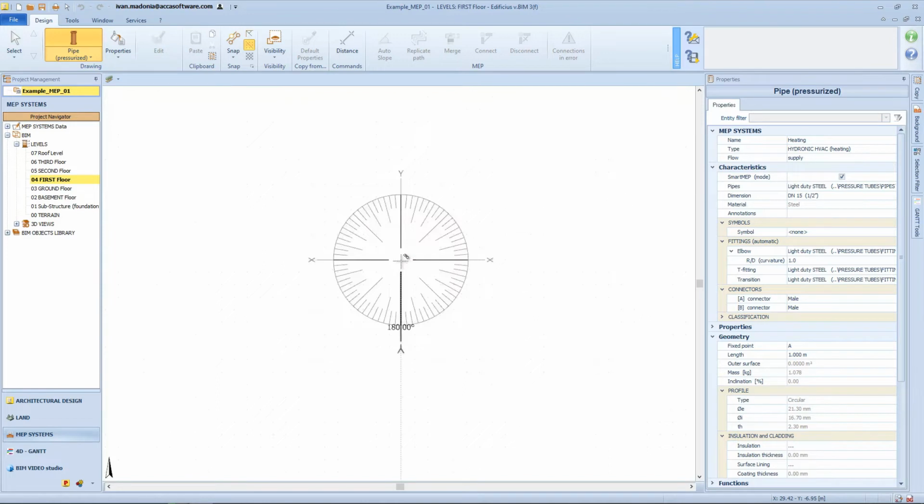degrees along the Y-axis. From the starting point of the pipe, by moving the mouse towards the circumference of the goniometer, the secondary angle snaps, identified by multiple angles of 45 degrees, are intercepted first, followed by multiples of 15 degrees and multiples of 5 degrees near the circumference.